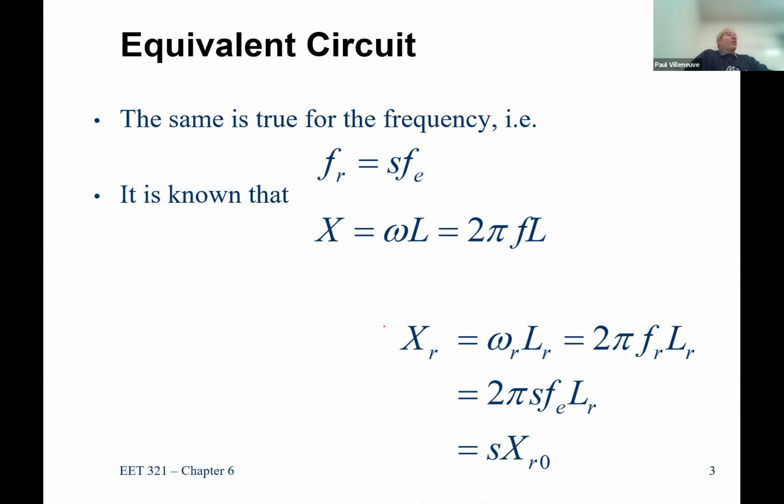They operate in sync with each other, right? So if the stator frequency is operating proportional to whatever the 60 hertz conversion is, the rotor frequency also has to operate at 60 or proportional to 60 hertz. And if you recall, when we talked about induction motors, the induction motor is spinning at a speed, so the difference between the stator magnetic field and the rotor magnetic field makes up that difference, okay?